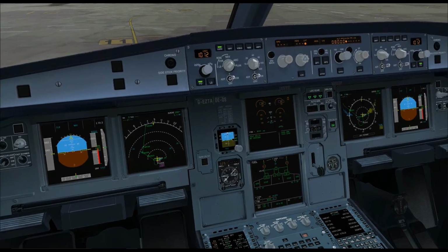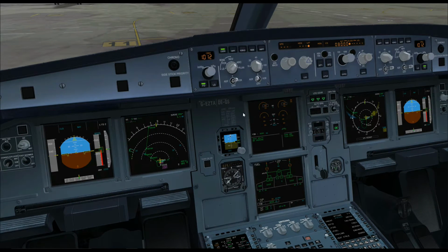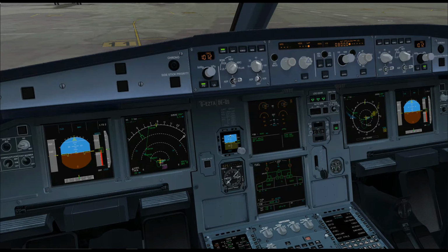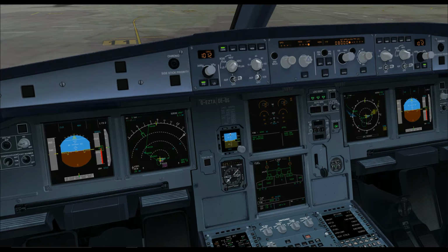We have no flags on the instruments. We can select on the navigation display the navigation aids as required, so we have Brecon VOR now on the left showing on the navigation display, and on the right in the green indication we have the Bristol NDB. And on the altimeters we have a QNH of 1012, which gives us about 630 feet, which is right for Bristol. Cross-checked on the first officer's side, 8,000 blue becomes flight level 80 at the transition altitude of 6,000 feet. So at this stage we can run the before start checklist to the line.